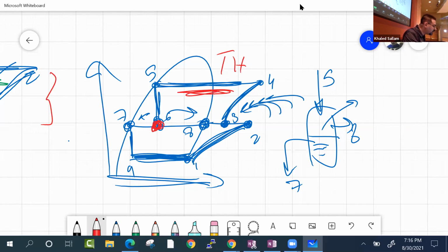We can take some of this vapor and cool the compressor with it. And now, amazingly, this plus this is way smaller than this. Had we gone all the way in one stage compressor, that would be more work. But doing it in the first compressor, cooling, and then going to the second compressor will cool down.